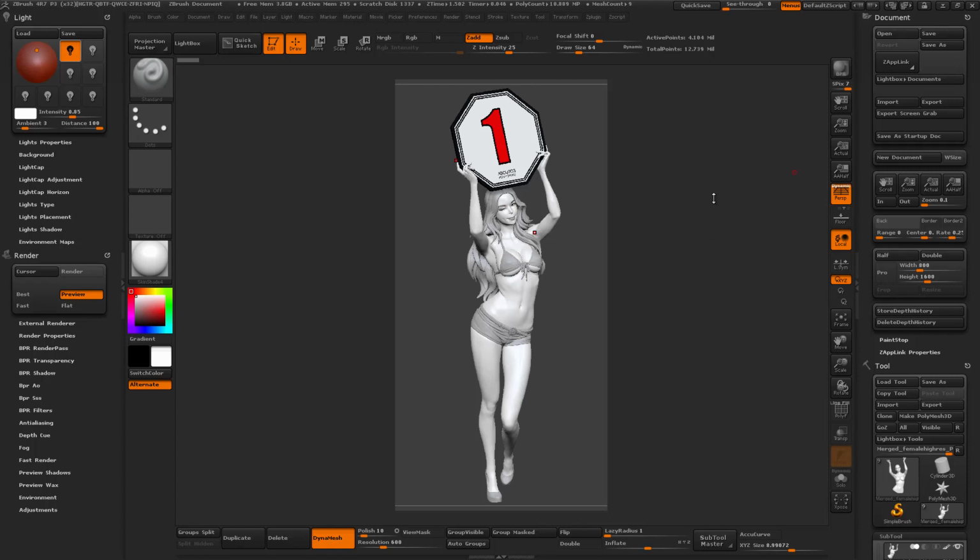So first, our render button is this BPR render. Its shortcut key is Shift-R. Under the BPR render button, it has a value for anti-aliasing. The maximum value is 7. The minimum value is 0. So the default setting is 3. When we are rendering initially and checking the effect, we can turn off the anti-aliasing and set it to 0. In this way, we can quickly and conveniently see the approximate effect of our rendering. Then we can set the anti-aliasing value back to 7.